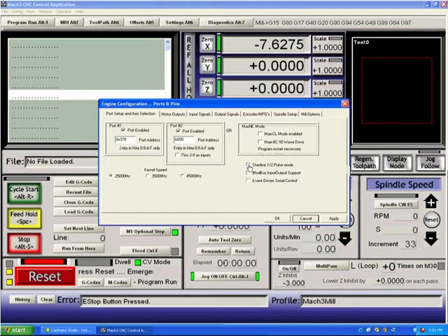Most do not need it, and don't use it unless you have a Sureline. For Modbus input-output support and event-driven serial control, leave them off until you've reached a state of expertise in using Mach3. They're not required unless you're using PLCs and other serial control equipment, and they will affect your system slightly in performance if you use them when you don't need them.